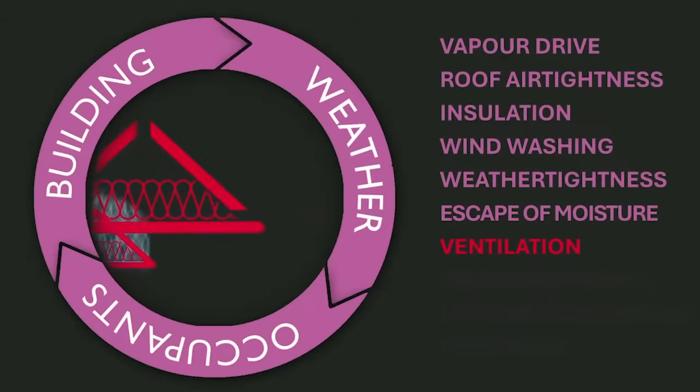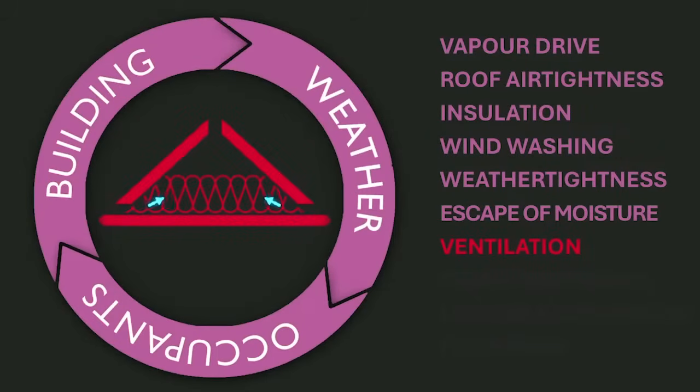Whether or not roofs and lofts require ventilation has been the subject of a long-running but now largely settled debate across the industry since vapour-permeable underlays first gained mainstream acceptance in the 1990s. BS 5250:2021 does not address situations where ventilation is omitted, but in section 12.5.3 refers designers to UKCA or equivalent accredited third-party technical approvals for guidance where a non-ventilated approach is taken. We'll come back to this later in the presentation.